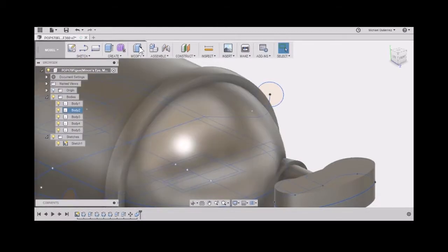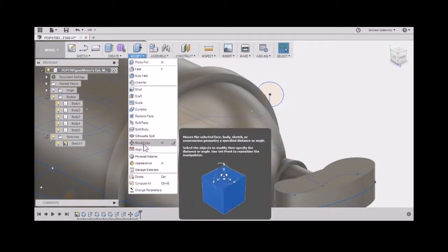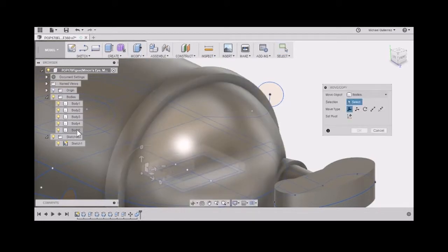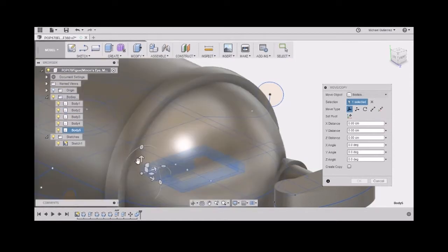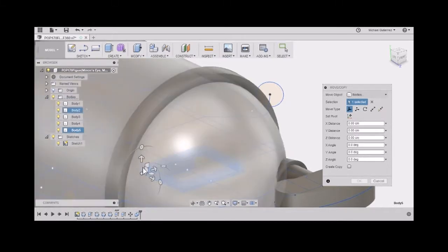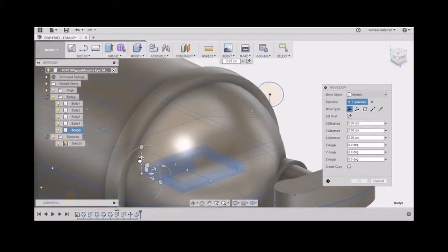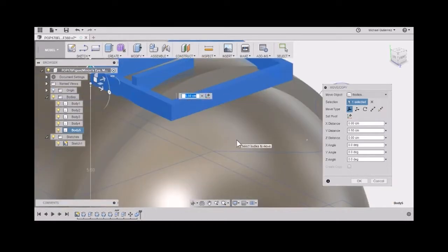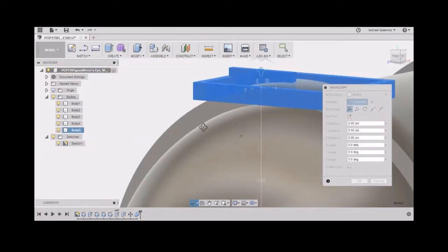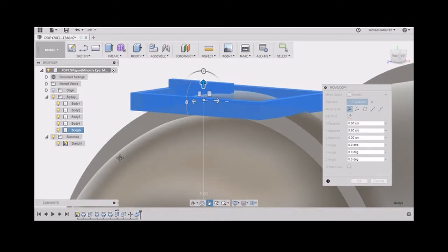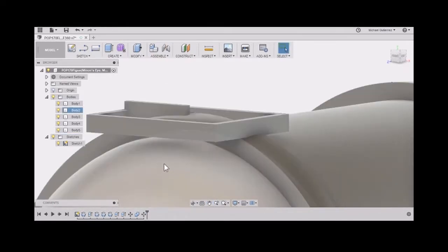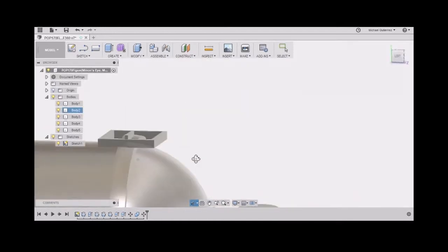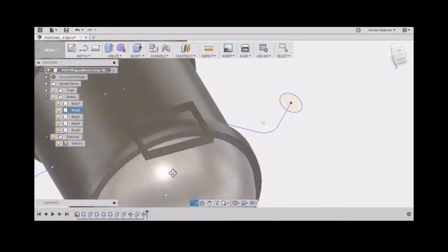So what we're going to do is modify, move, select the last body, which is body number 5, the belt buckle body, and grab this. You can either grab this out or use the numbers over here and move it. Like so, and I'm just going to leave it as 5.5. You guys see in both directions, and hit OK. You can move it as much as me, or you can move it more down.